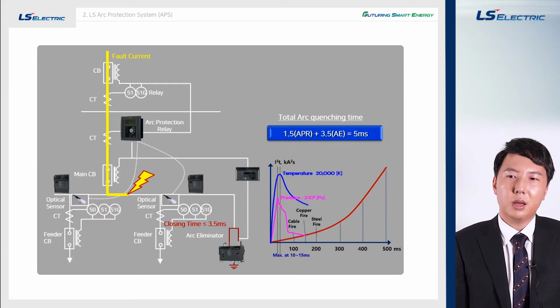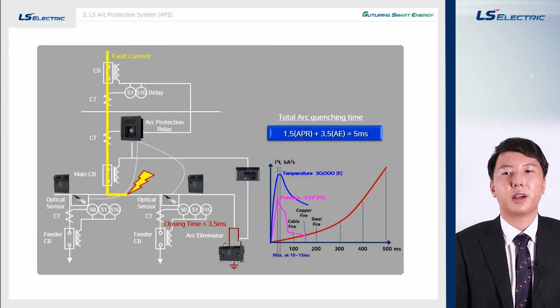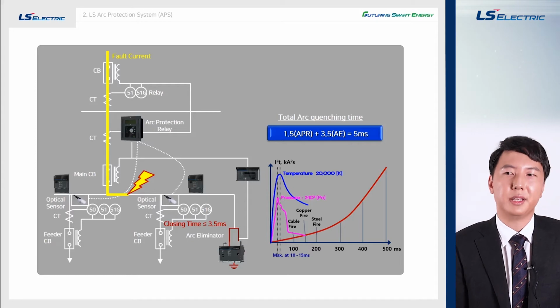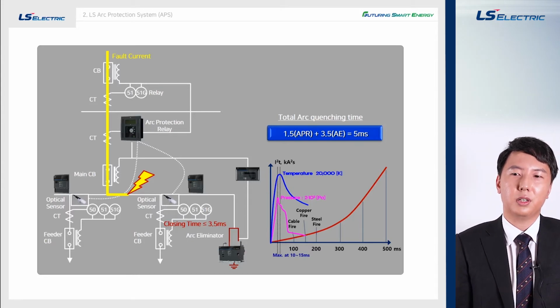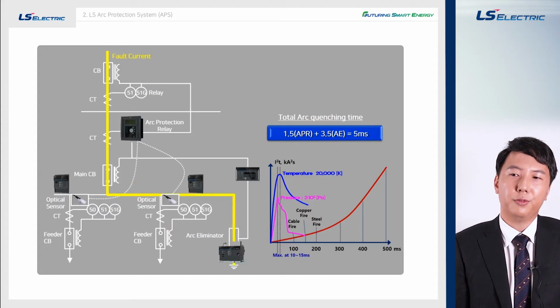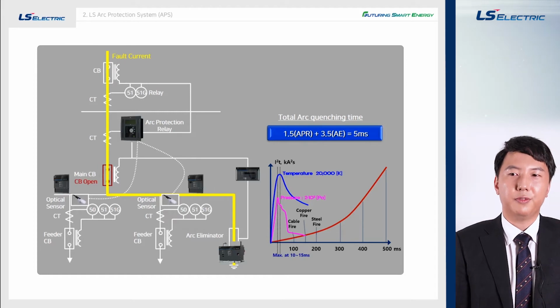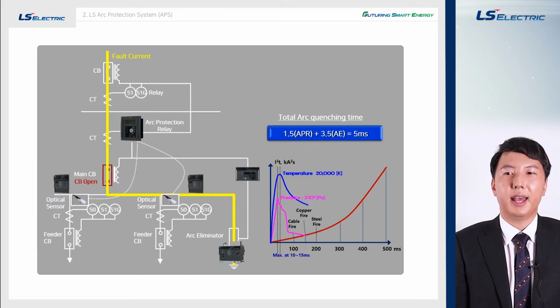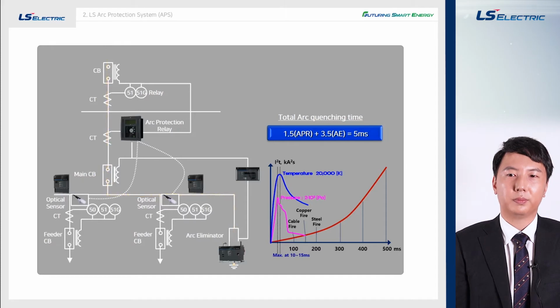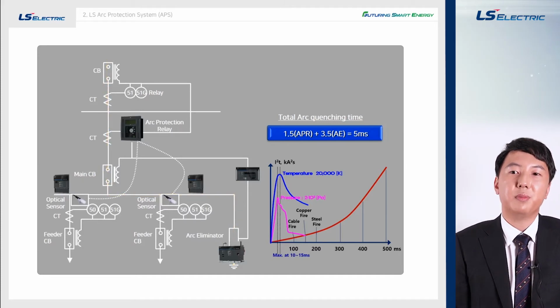In other words, because the short circuit and earthing carried out by the arc eliminator has a much lower impedance value compared to the impedance value of the arcing point, the fault current will flow to the arc eliminator. The circuit breaker operation sequence will take place within 3 to 5 cycles. The incoming VCB will open the circuit and the situation will be cleared. During this process, arc energy will be extinguished within 5 milliseconds.